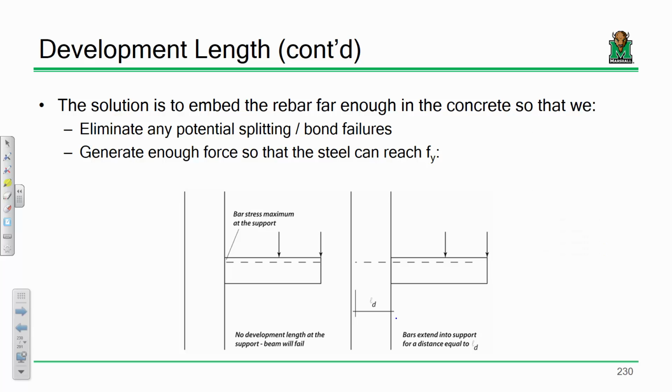Okay. So again, just to emphasize, and I'm going back to this example that I think I showed you all earlier. If you have a cantilevered beam, we know now that the rebar goes in the top, right? The top region is seeing tension. But if we just had the rebar in the top and we stopped it right here, just think about this from a physics perspective. You take that beam, you're applying vertical load, you're bending that element. That element's wanting to bend down like this. If that rebar isn't tied back into that adjacent element, this is just going to fall right over. That piece of rebar has to be embedded into that adjacent element some specific amount.